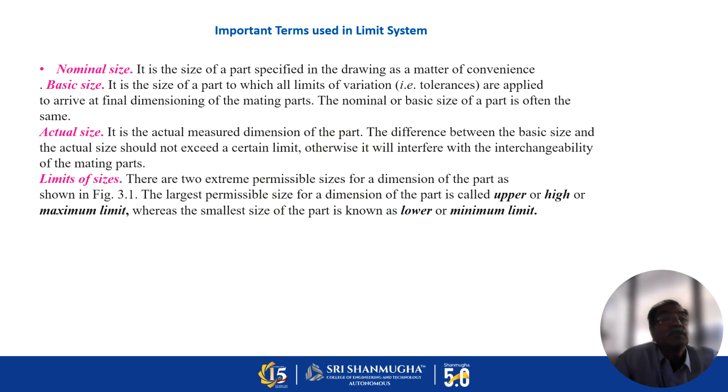Next is actual size. It is the actually measured dimension of the part. The difference between the basic size and the actual size should not exceed a certain limit, otherwise it will interfere with the interchangeability of the mating parts.